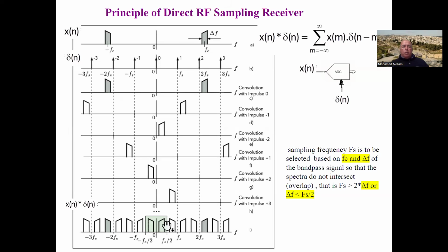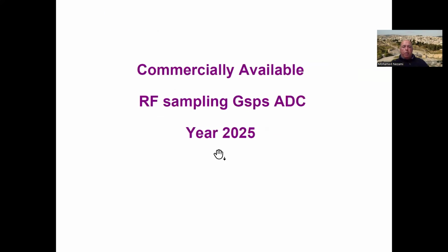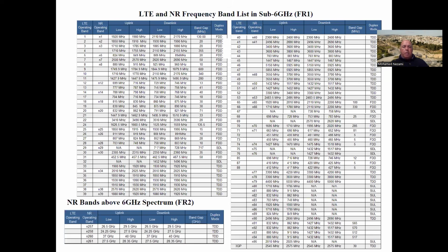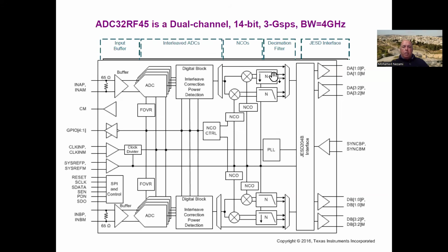Of course, you don't care if it's inverted; the inclined sign in here means the inversion, to keep track of which one is inverted. Spectrum inversion in the digital domain is pretty simple: it's just sign changes on the I's and Q's. So when we shift this, we need to get rid of the other replicas, and that's what you're seeing in these filters.